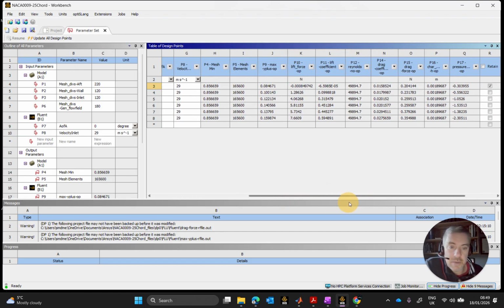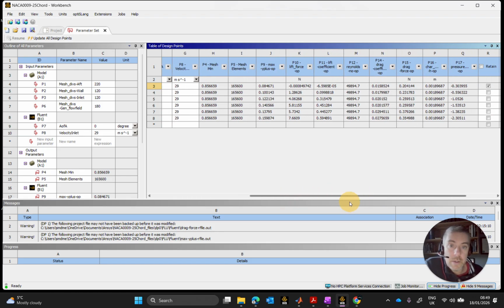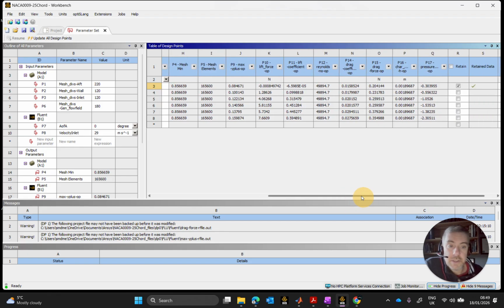And that's what I'll do in this. Now, adding in more than one additional metric as part of my convergence condition, that is fine, because I'm not changing anything. I'm just running it longer, and I'm ensuring that the value that I have is a solid final value for that set of solutions across the fluid domain.